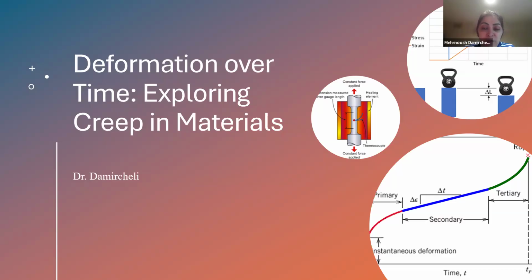If I want to explain briefly the difference between stress relaxation and creep, I should say that while creep focuses on how a material deforms under a constant load over time at high temperature, stress relaxation looks at how the stress in a material decreases over time when the strain, or epsilon, is held constant. Both phenomena are important in designing components that operate under high temperatures or long-time loads, such as turbine blades, boilers, and pressure vessels.